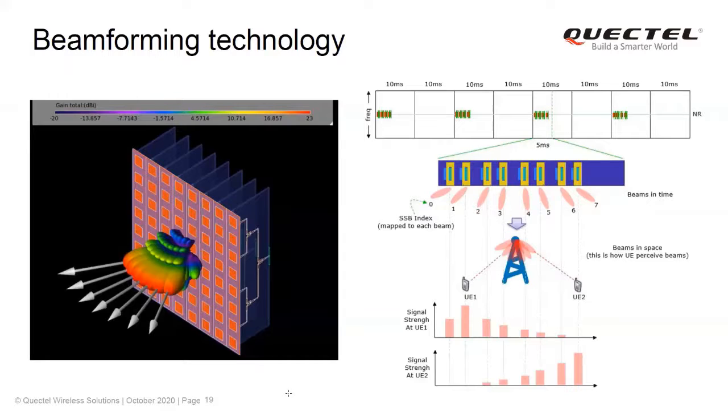So each device, each UE, works okay, but with different beams. We could say these are different antennas, but it's the same antenna using time multiplexing. It's communicating with each device at different timestamps. It doesn't beam at the same time in all directions, because this wouldn't be beamforming, it would be an omnidirectional antenna. It's beaming in one direction at one specific time.